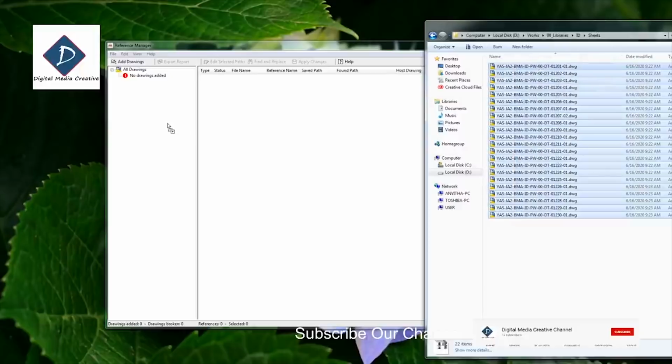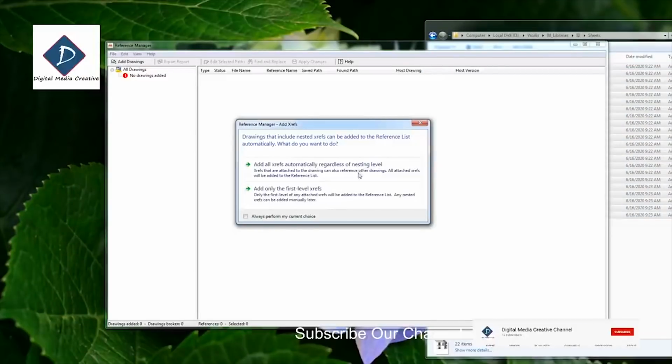Okay. Just drag and drop here. So it will ask which option you want. But normally I will add only the first level xref. So it will not hang, or it will not take more time. So it will be too fast. Okay. So I'm just going to click on add only the first level xref.